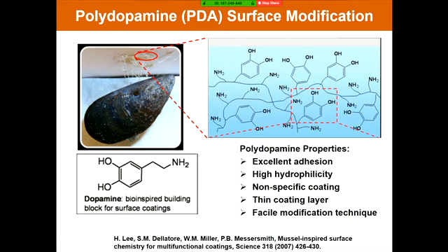They used the dopamine molecule as a surrogate or a representative of these types of functional groups, and found that when this compound was oxidized to form a compound in the literature known as polydopamine, it would adhere to virtually any surface, and this would include steel, plastic, ceramics, semiconductors, and so forth. It would coat those structures out of aqueous solution in nanometer layer thicknesses, and it rendered the surfaces hydrophilic, and this is the piece that caught our attention in terms of a fouling resistant coating.